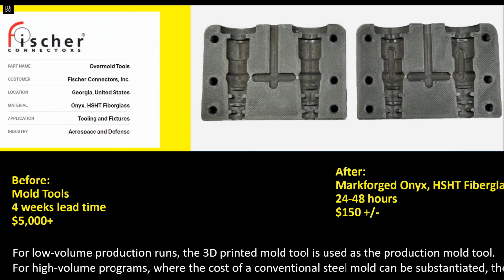Fisher Connector is a manufacturing company in Georgia that creates overmolded connectors for aerospace and defense. For a typical mold tool for an overmolded connector, it takes about 4 weeks of lead time and around $5,000 to create the tooling. By utilizing Markforged Onyx and high-strength, high-temp inlaid fiberglass, they were able to reduce the lead time to 1 to 2 days and only $150 in tooling. For this specific case, Fisher actually uses this 3D printed mold tooling as their production mold tooling.